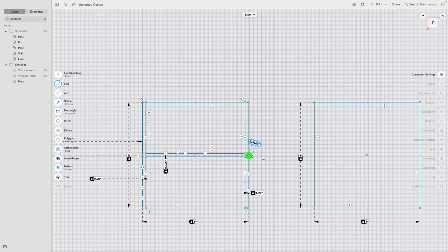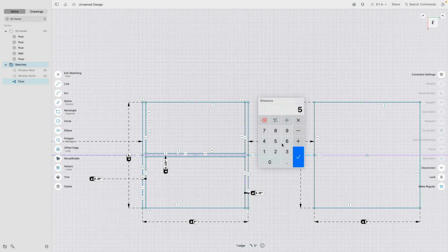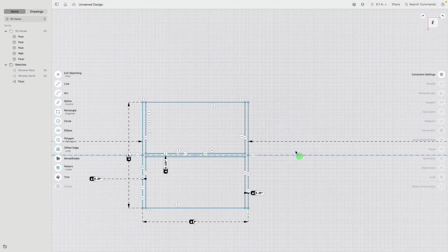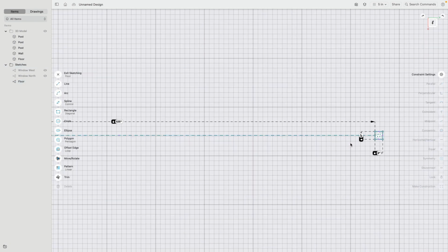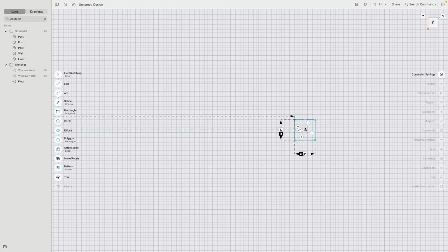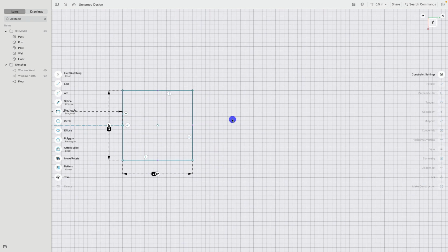I do not draw all the other stuff in it. I don't need it. I'm actually creating here kind of like a guideline, horizontal, and then this also should be a construction line, and then this line we set to 525 and enter. Cool. Okay. Because this is a rectangle, later when I extrude the I-beam out, I can just move and snap it right onto a corner. So I don't have to draw all this other stuff.